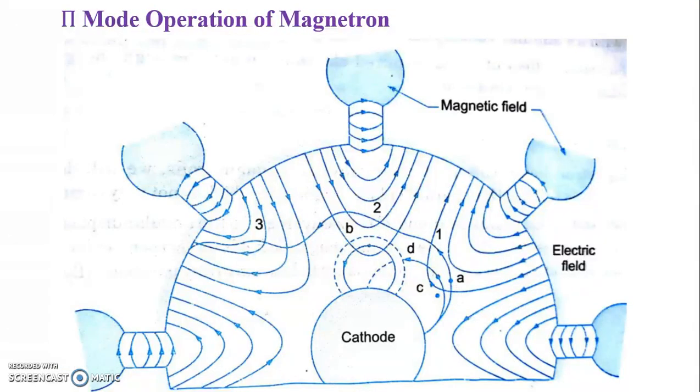All the previous explanation is for a static case, in the absence of RF field in the cavity of the magnetron. Assume that RF oscillations have been initiated due to some noise transient within the magnetron; then the oscillations will be sustained by device operation.